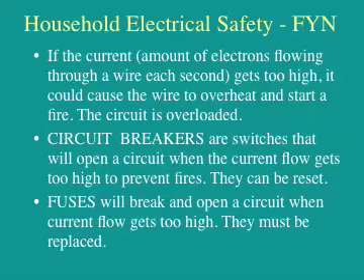Circuit breakers are switches that open a circuit when the current gets too high, and they do this to prevent fires. If the current gets very high and the wire starts to get hot, the circuit breaker will open the switch, which opens the circuit and stops the flow of electrons and lets those wires cool down. One of the nice things about circuit breakers is that if they open, because you've overloaded a circuit, you can go reset them. Typically this is done at a circuit breaker box that you'll find in the basement of your house.